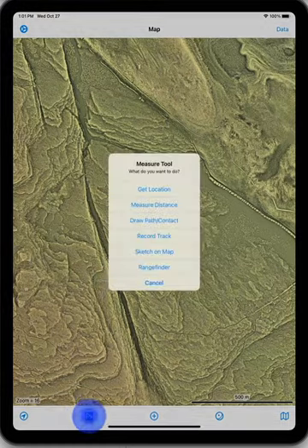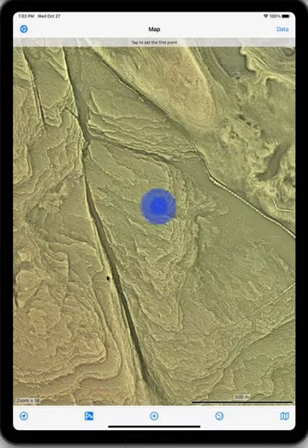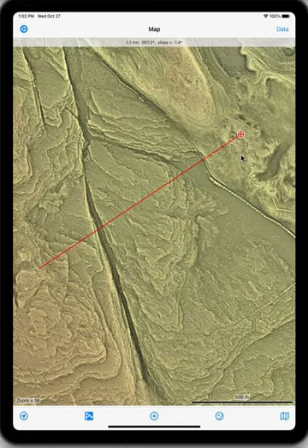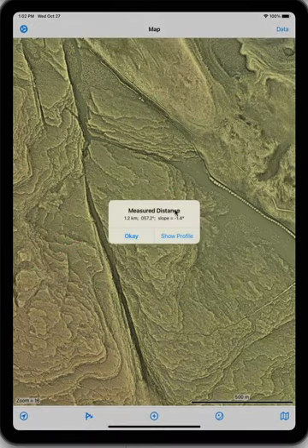We can also measure distances. To measure distances, you tap and drag to set the first point, and now you tap and drag, and you can see the red line is showing you the distance between the 2 points, and at the top of the map, it shows that you have a distance of 1.2 kilometers on an azimuth of 0.57 degrees and a topographic slope between the beginning and end point of minus 1.4. When you let go, that same information is reported to you here.